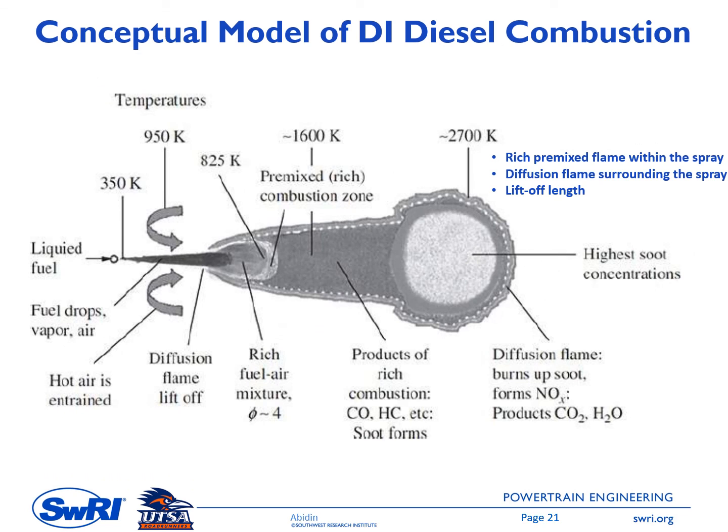Okay, and then we can see in more detail the structure of this flame in the next slide. So we can start from the left side. At this timing, the liquid fuel is still injected from the left side, and then there will be atomization because of the velocity difference between the liquid fuel and the surrounding air, and then the surrounding air, which is hot here, is entrained by this high velocity liquid and enters the fuel spray here.